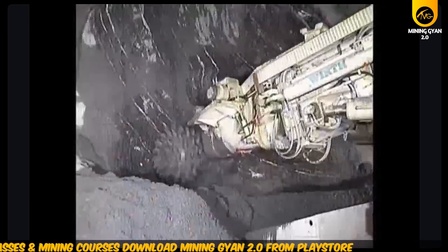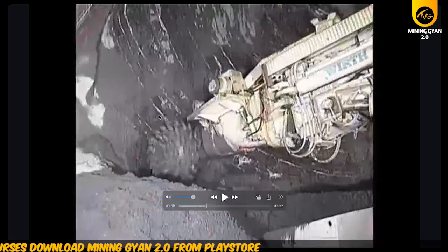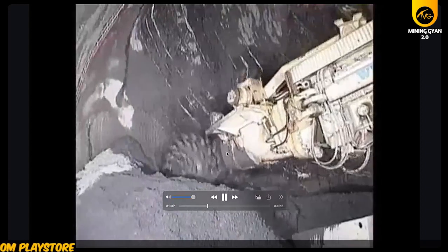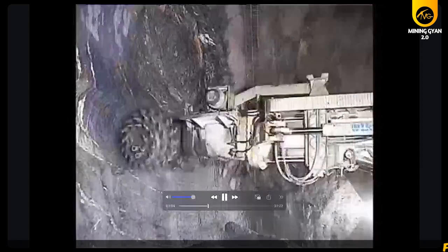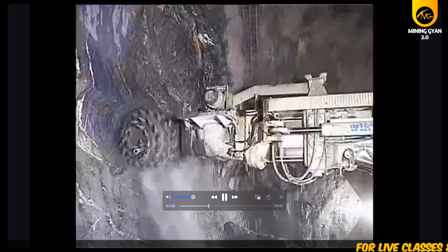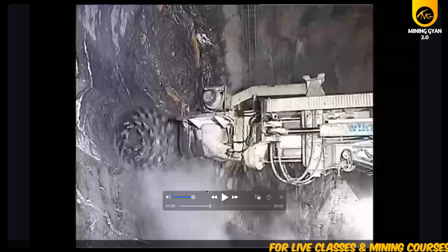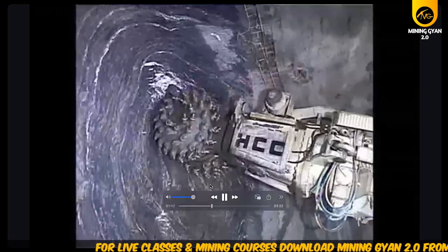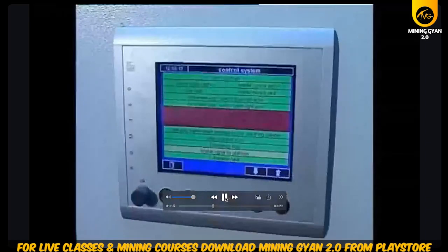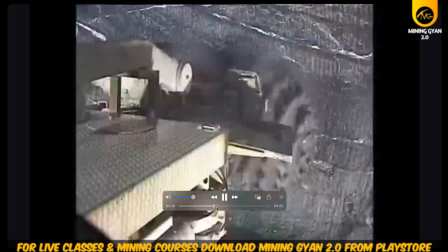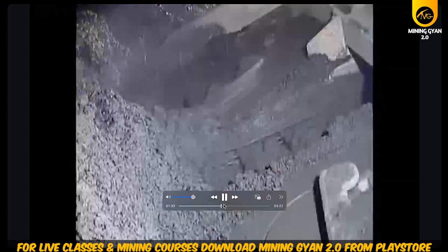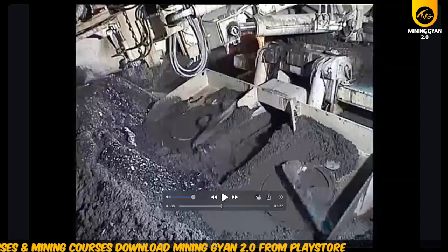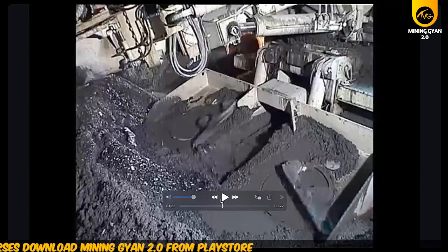So this will cut your rock, which depends on your rock property. Currently more than 60 MPa. The cutting starts with road header at the center position. So it will cut down your rock. Facilitates smooth and accurate cutting with less overbreak. A software-based profiling system has been used. These are your gathering arms which collect the material and put it on your chain conveyor.